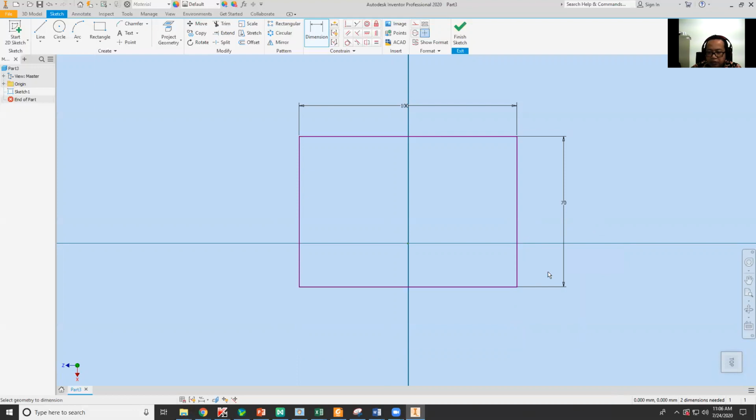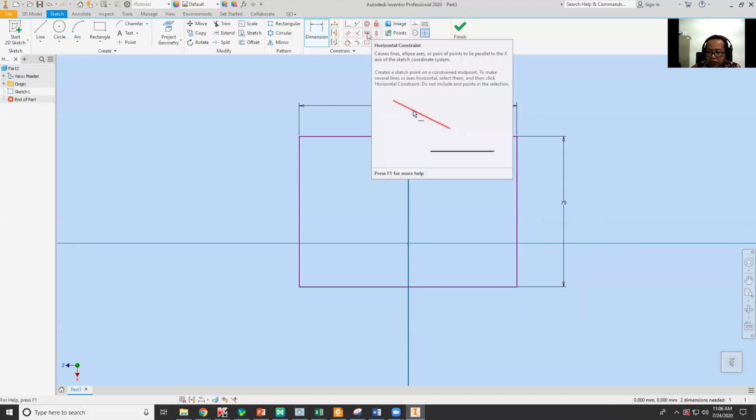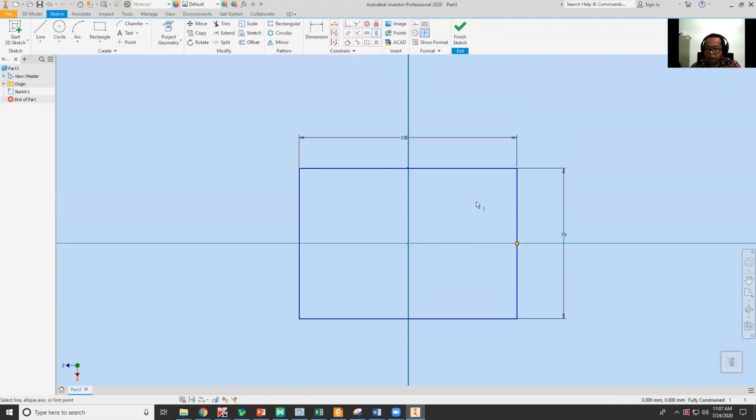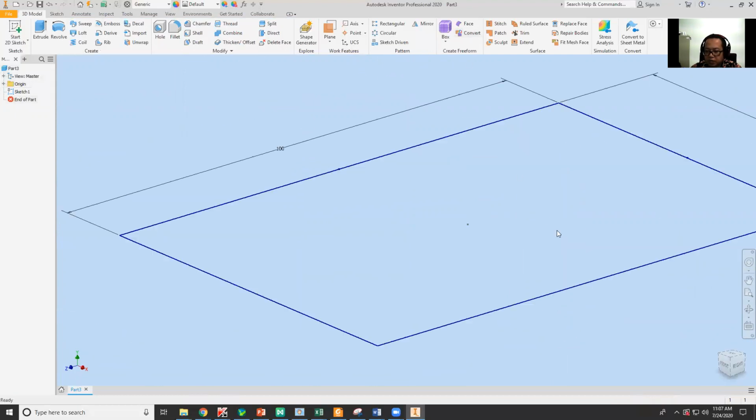All right. Now we can make it in the middle, at this point. Just remember our previous lesson, we used horizontal. We go to the horizontal line. This one is already in the middle, right? I repeat, click center and click here. This one is already in the middle. So we want to make this vertical equal in the middle of this line, at this point. Click vertical, just search for the middle of the line, click here, and you can click this one also. So it will go to the middle, right? The next step is we click finish. Click finish. Okay, scroll down again.